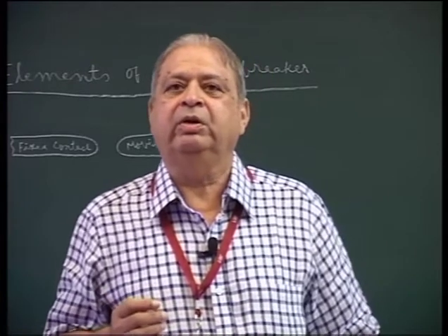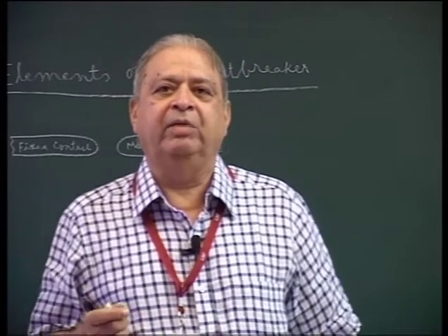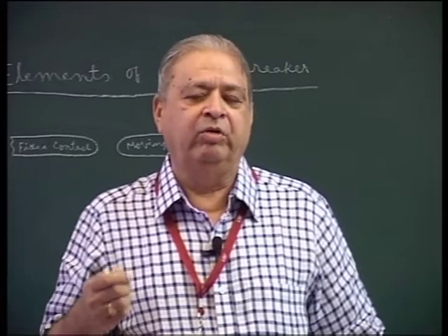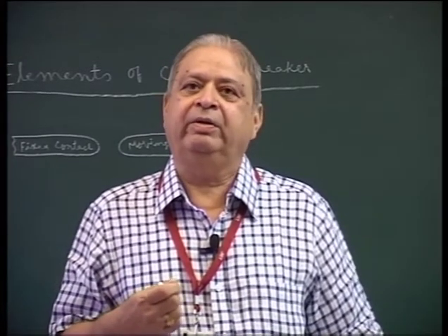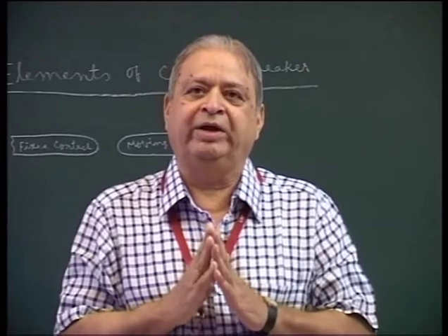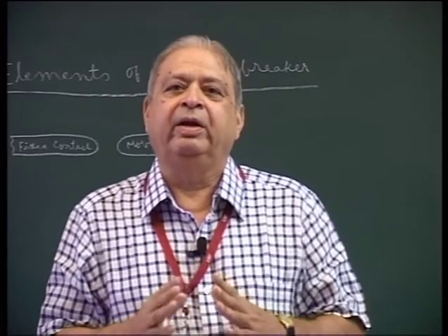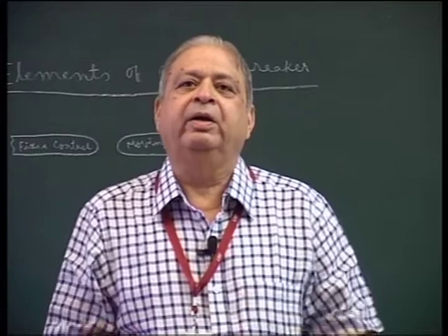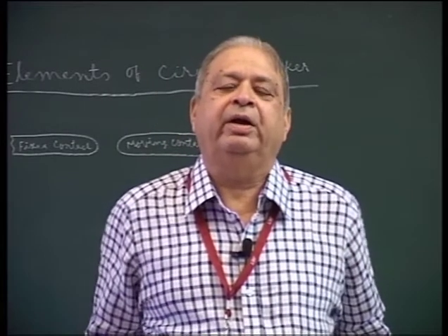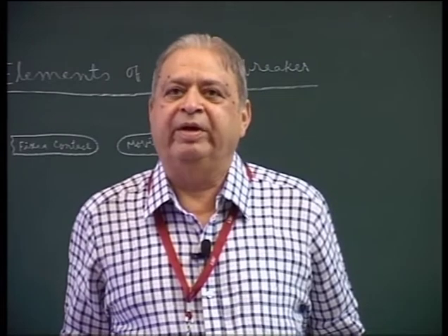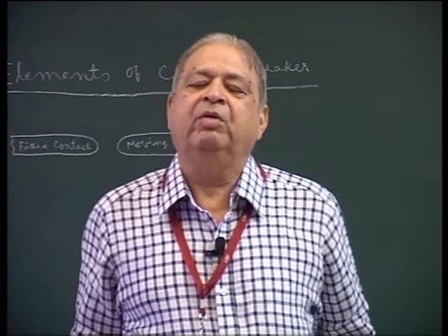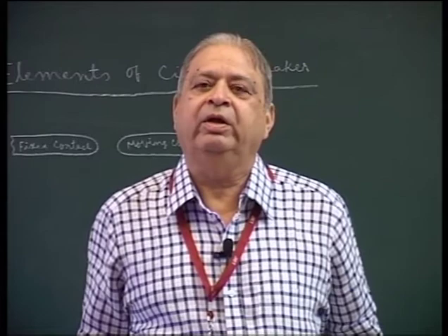This is because silver is malleable, and when the moving contact presses firmly over the fixed contact, the silver gets flattened out and the area of contact between the fixed contact and the moving electrode is maximized. That gives minimum ohmic resistance of the circuit breaker.